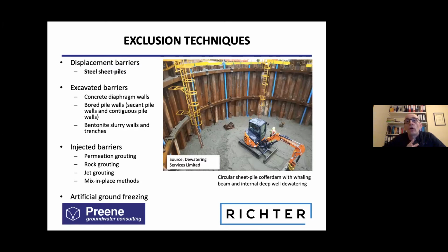And the most common form of creating such a barrier are the steel sheet piles, which many of you will have used. The steel sheet pile method involves taking a steel section that's set vertically underneath a crane typically, and is either driven, pushed, or vibrated into the ground. And a series of sections are installed next to each other, and they connect to each other via a clutch or an interconnection, so that this series of individual sheet piles can form a continuous barrier.